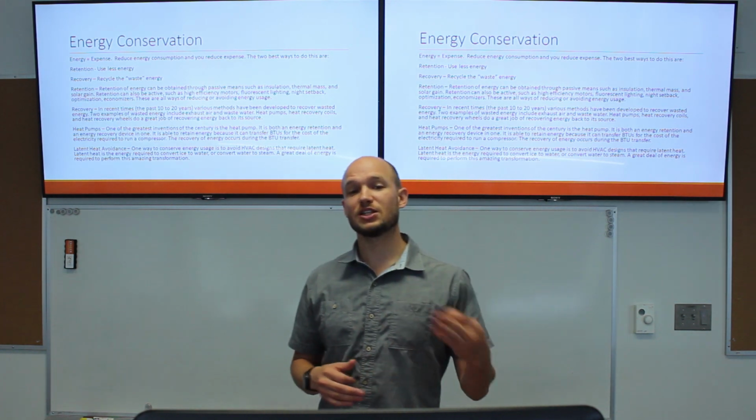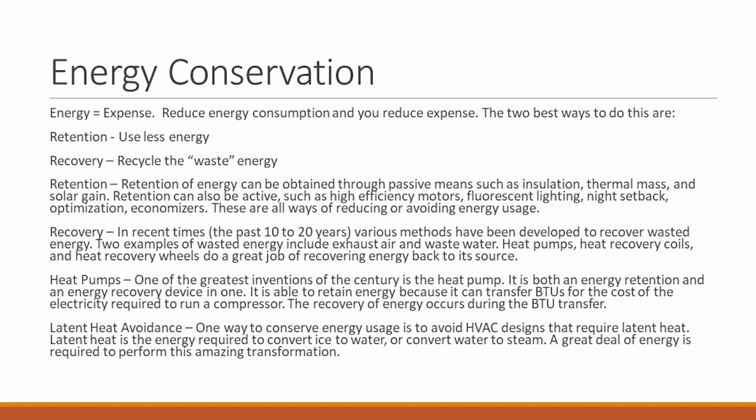And so retention and recovery are two ways that you can reduce this. So retention is going to be obtained through passive means: insulation, thermal mass, solar gain. Can also be active, such as motors, different lighting, night setbacks, optimizations, etc. Now recovery in the past 10 to 20 years has really gone up in developed methods. And so what we're talking about here is heat pumps, heat recovery coils, heat recovery wheels.